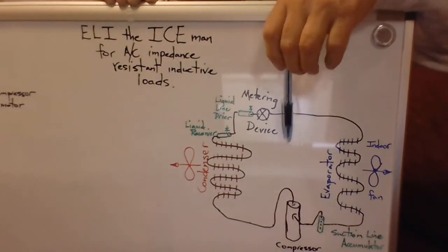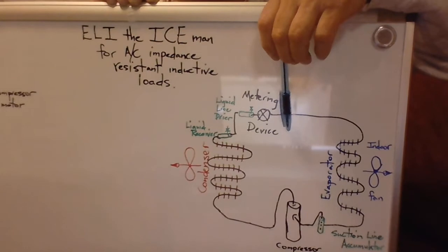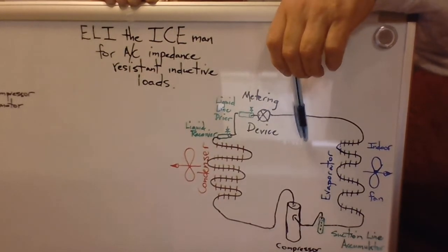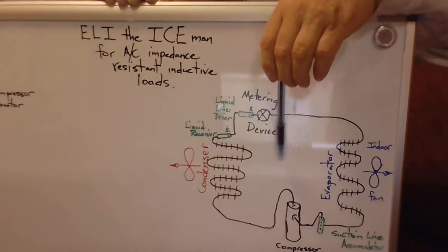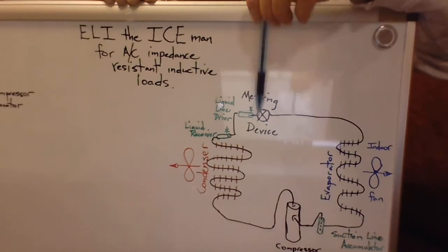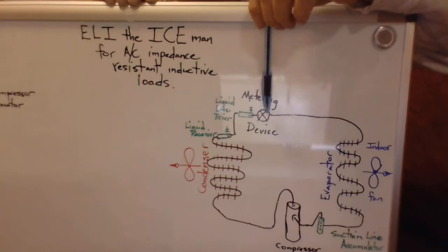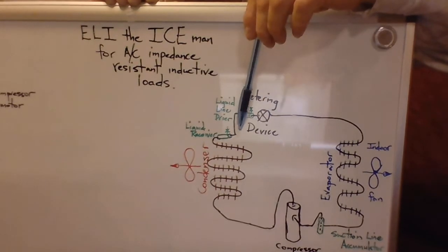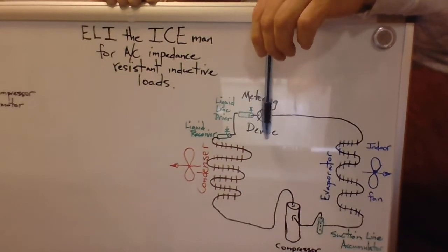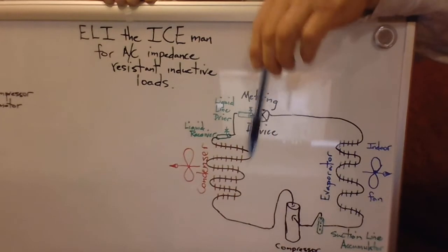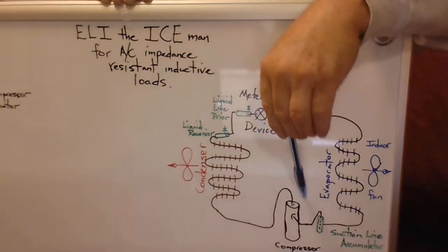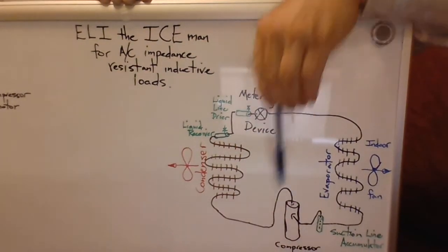So too must you learn to ascertain through the various subcooling, superheat numbers and discharge superheat to establish what might be the difference between an overcharged system and a dirty coil, because they may have very similar symptoms, but the discharge superheat is going to be way different on one application versus the other.